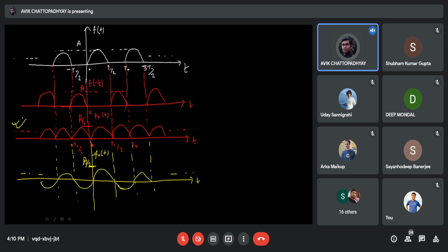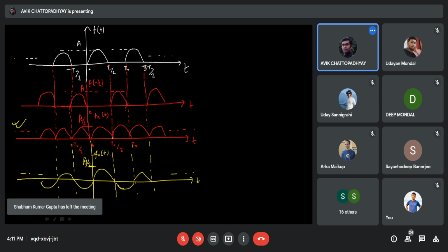I will just calculate the DC term. And there will be cosine terms because this is even. And not only is it even, it also has half wave symmetry in the even sense. That means not only the cosine terms will be present, but only the even order harmonics of the cosine terms, because this part manifests half wave symmetry in the even sense.